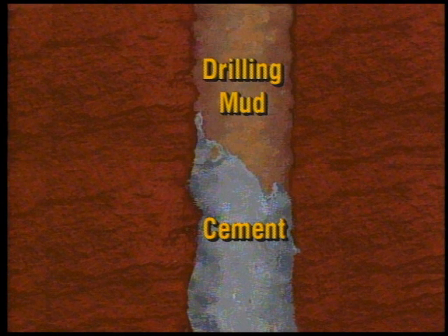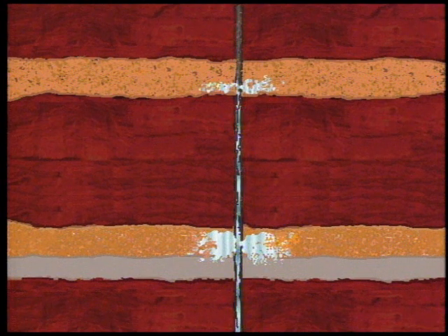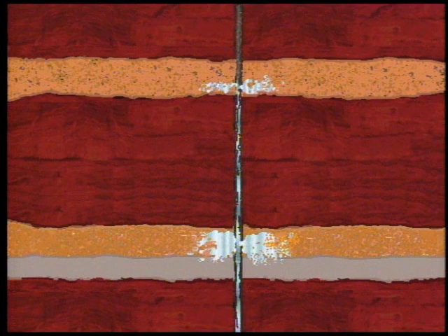However, even with an improperly plugged well in the area, other forces, in many cases naturally occurring, impede the vertical movement of injected fluid up the well and into freshwater sources. These forces include collapse of the wellbore, drilling mud or cement in the borehole, the presence of downhole equipment such as packers left in place, and the existence of other permeable formations located between the injection zone and freshwater sources to divert the flow of fluid.